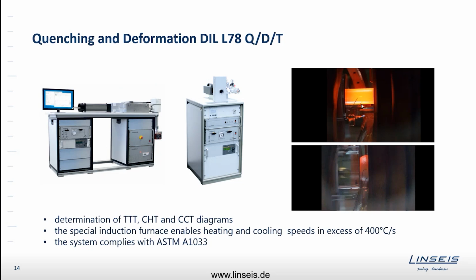If you apply a modular magnetic field, so it can be adjusted, you can reach very fast heating. So it's induction controlled. The temperature of the sample is monitored by this thermocouple that's in touch with the sample directly. You measure the heating, and out of the heating of the sample, the system can very fast regulate or control the power of the magnetic field and the power input. Therefore, you can create any kind of temperature profile, and you can heat and cool in very, very short times.